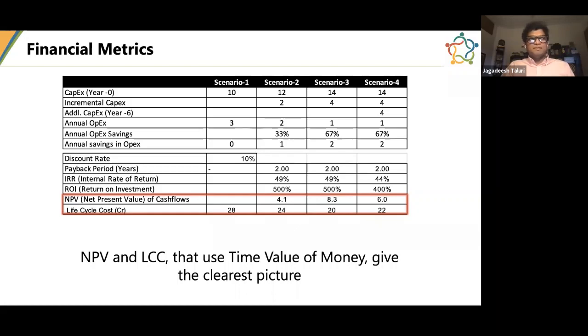But payback period is a blunt instrument. If you are trying to take a much deeper look into how you are going to propose your options, suppose you are evaluating a conventional VAV system, you have done the best you could do, but you're not able to make it net zero ready. You may have to use a radiant system, insulation and all the other things. For some of these aspects, you may not be able to calculate a payback period to the finest degree. In all those scenarios, life cycle costing is usually what gives you the advantage to illustrate to your project partner how you are adding value, and how it's in their best interest to take the proposal that you are giving them.